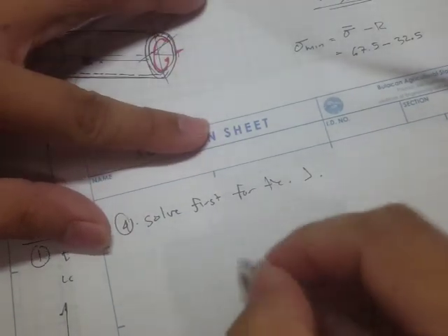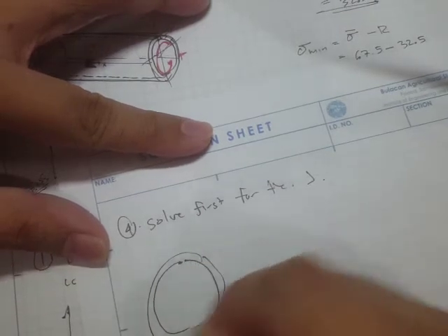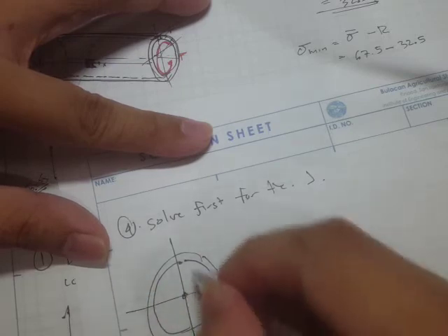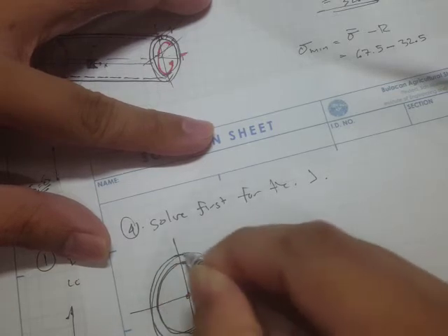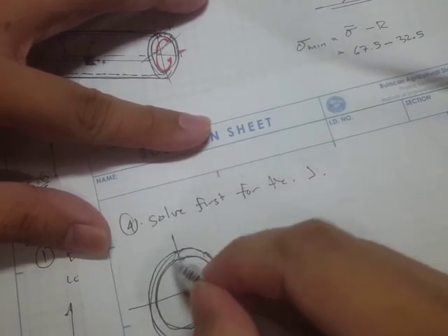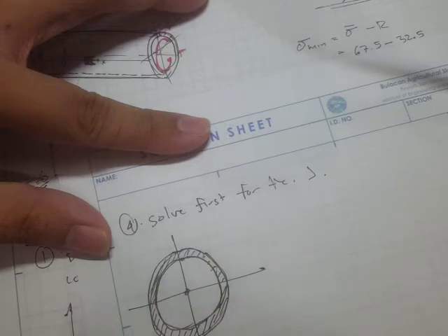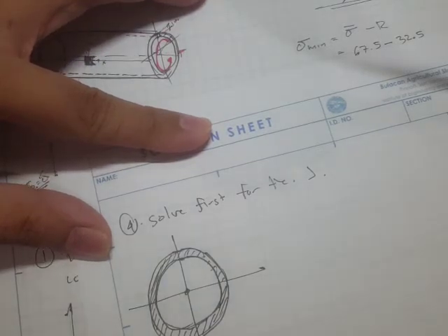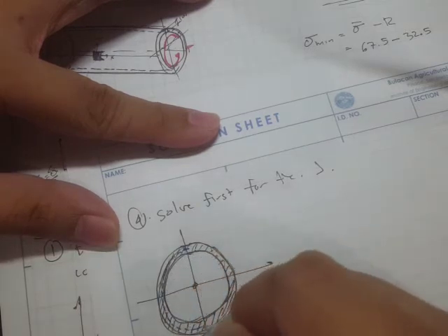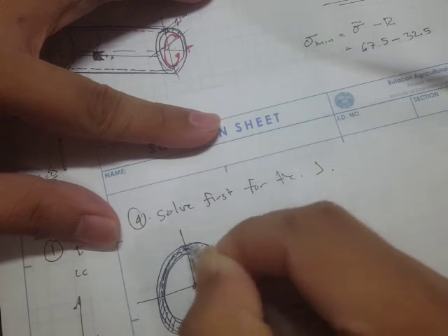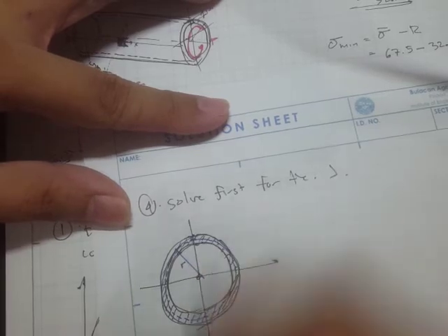So the polar moment of inertia is actually something like a resistance to rotation. And if this is our cylinder, and take note of the word thin-walled cylinder, and we are considering this area right here, we have the mean radius, and that's going to be in the midpoint of the outermost diameter and the innermost diameter. That's going to be our R, right?